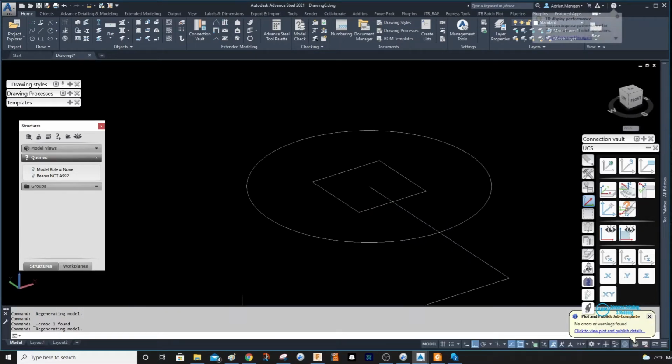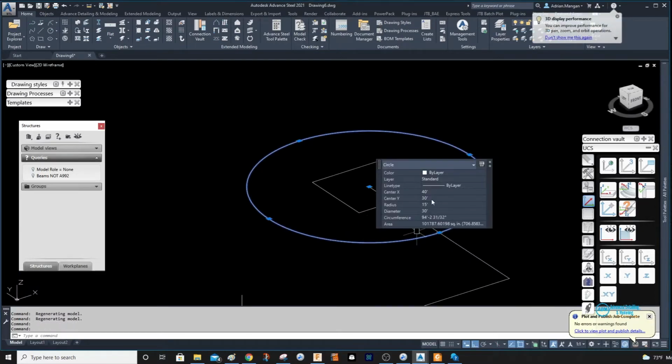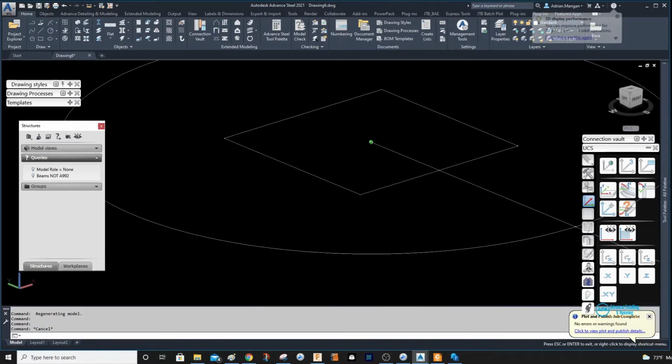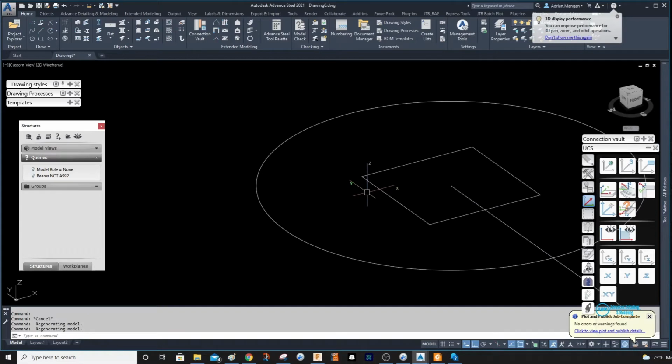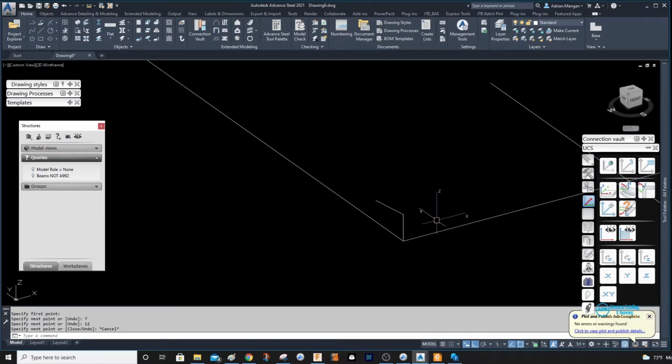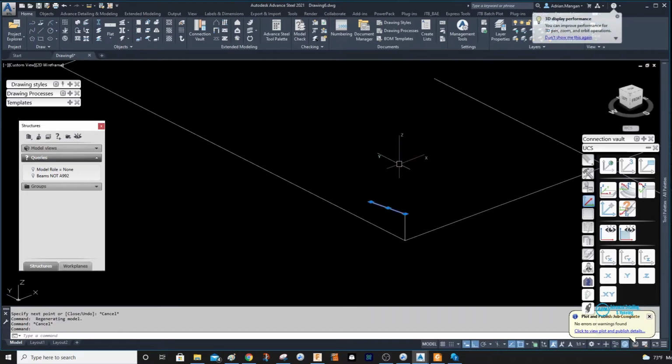So we're just going to start with this simple. This circle is like a 15-foot radius, and this is 10 feet around each square here. Basically, it's similar to stairs I did recently. So we'll keep it simple. This is 10 feet. I'll do a 7-inch rise and a 12-inch going, which is a lot, but it's definitely used on these types of stairs.